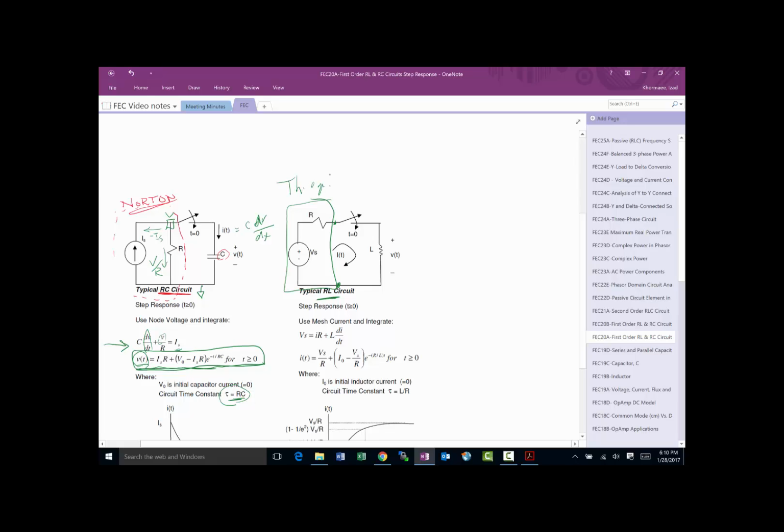Okay, and then if we were able to get our circuit to look like a Thevenin equivalent, we'll be all set. And if you look over here at time t equals 0, the switch closes. So the inductor had nothing in it for a while, so its initial condition is 0 in this case. But then as soon as we close the circuit, this voltage appears here. And we know from our conversations before that inductors, when you put them in, act like an open, and over time, when things stabilize, they become a short.